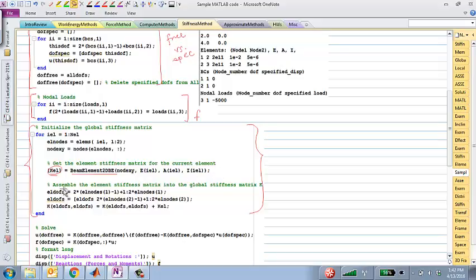And after that point, you assemble the global stiffness matrix. So I'll call that K global is equal to sum or some sort of an assembly of K M, where M goes from 1 to number of elements. So this is just an interpretation that you're adding up all of the individual elements into the global stiffness matrix, exactly the same way that we did for the truss elements.